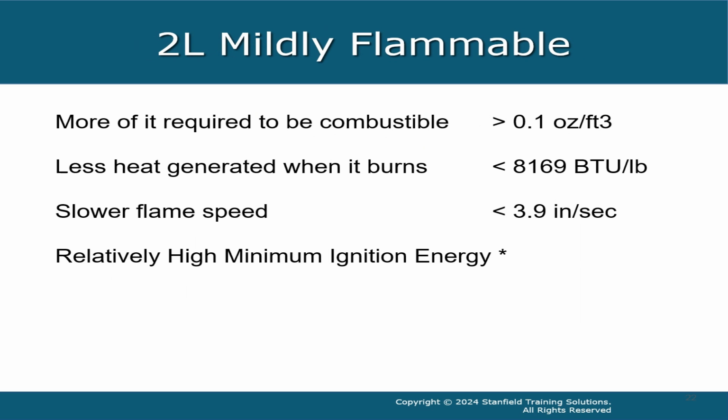Here are the Category 2L requirements listed in imperial units. It takes more than 1/10 of an ounce per cubic foot to make a combustible mixture. When it does burn, it creates less than 8169 BTUs per pound. The flame speed is less than 3.9 inches per second. And there's a fourth characteristic that I believe is just as important, and that is that the 2L refrigerants have a relatively high minimum ignition energy.